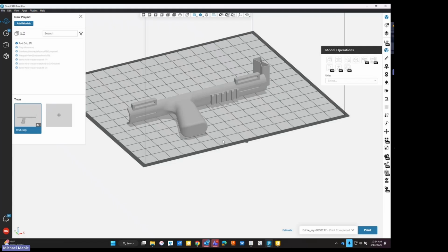Because there is actually a mechanical bond between the support and the model layers, the only way to remove it would be to mechanically sand it or grind it away, but then you're not rehydrating the part itself. You could just simply do that by dunking it in some water after the fact. But otherwise, when it's out in the environment, it'll absorb moisture from the environment. Unless, of course, it's really dry, like we get here in the wintertime.